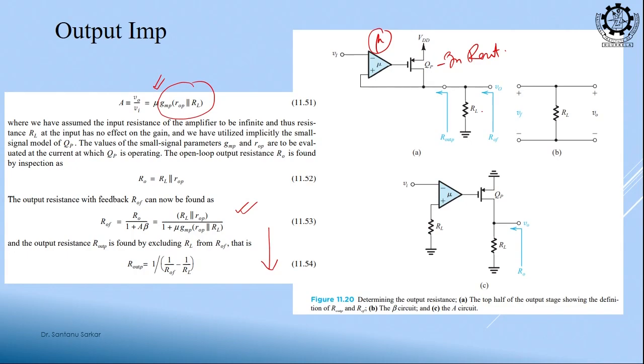Okay. So, efficiency of the class AB amplifier will also be close to the class B, and maximum efficiency is roughly 78.5%. Okay. You can repeat the class B efficiency calculation, because you know that the extra DC value is very small. So, if you neglect that, you can consider the same procedure: average power supplied from 0 to pi only, and you can calculate the average current and average power dissipation and then the efficiency, which will be roughly 78.5%.